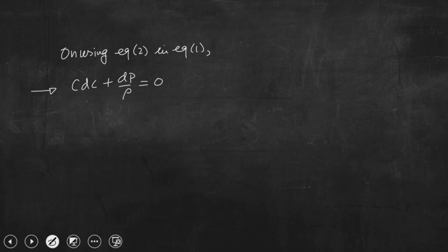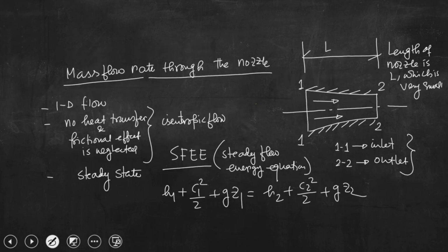Why do we need the flow velocity at the exit of the nozzle? Because we are trying to figure out the expression of mass flow rate through the nozzle, which is important at the exit of the nozzle. Mass flow rate at the exit should be density, velocity and the cross sectional area. The exit velocity is very important, because that velocity will dictate the energy of steam before it strikes the turbine blades. So, that is why it is very important.